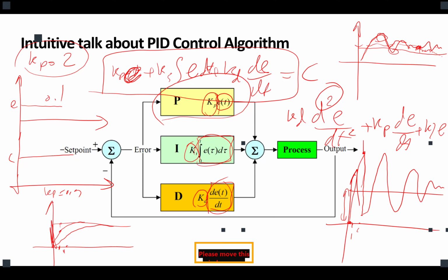Now, practically, when you want to tune that, normally if you don't want to auto tune, you would not manually tune. What they do normally is, for all three gains, they start small and try to find the optimal value by increasing the gains gradually. Because if you start big, then you have a lot of undershoot and overshoot, and your system might get unstable, or pass a certain threshold it can withstand. Are we good? So this is the practical tip.